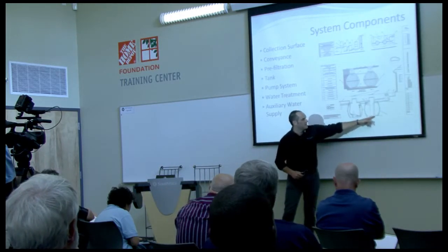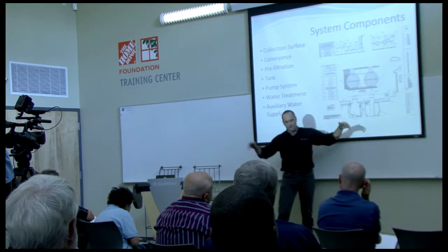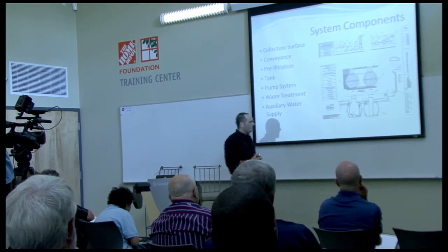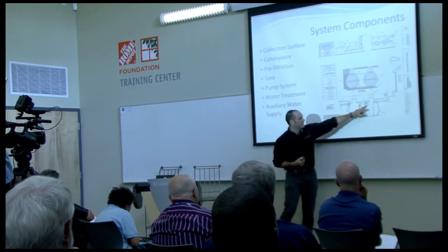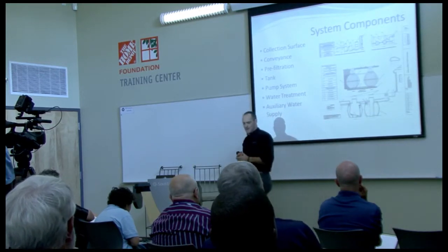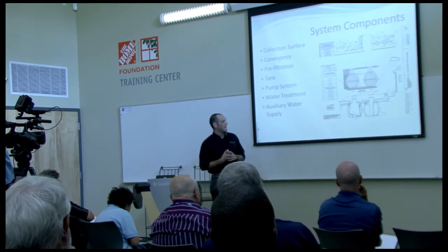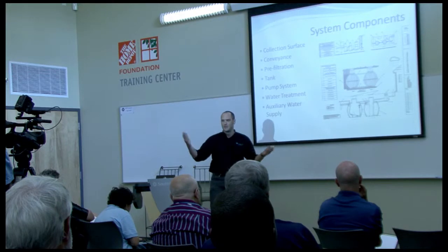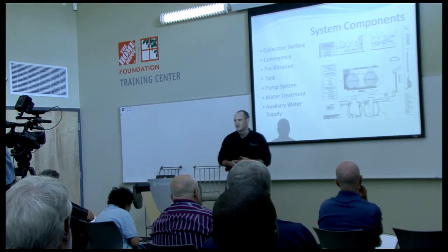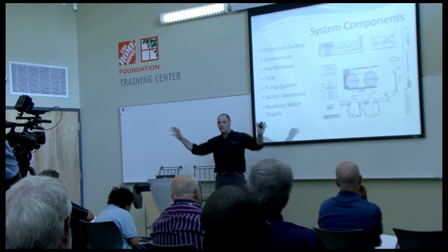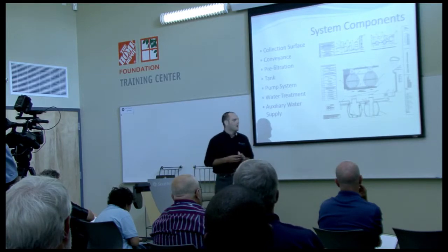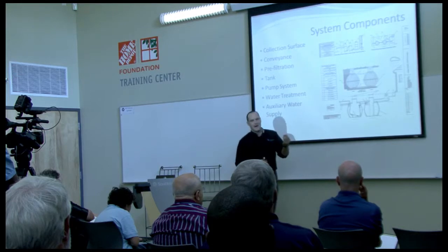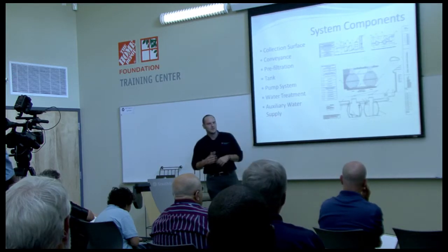So the water would flow into the tank and go through the calming inlet, which actually broadcasts the water up into the tank so you don't disturb the sediment bed. Then you move on to your overflow siphon, kind of looks like a P-trap there. So you have your sediment bed intact on the bottom, and there's some things that float on top. We call them floatables, so like pollen. If you ever look in some of these tanks in the pollen season, the whole top of the water level is usually yellow. Actually, as the sediment bed on the bottom starts to break down, some of that stuff will float to the top.